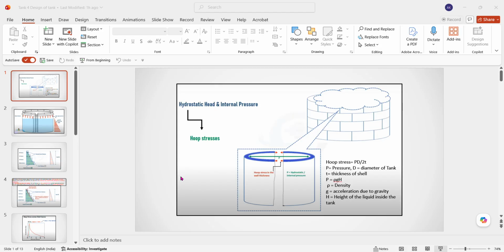So above it the stresses will be maximum, that is at the 1 foot height or 300 millimeter. Similarly, for the second course, the plate thickness is more, so this point will act as an anchor point. So again at 300 millimeter the stresses will be more, and here we have to calculate the thickness of the plates.